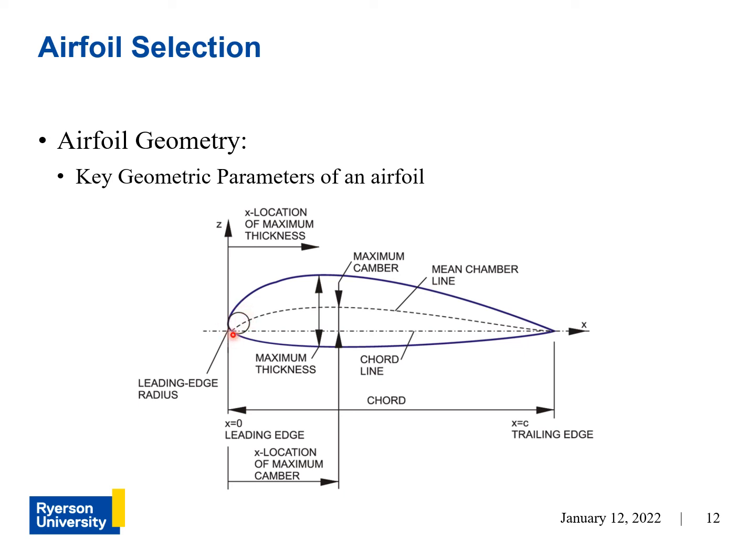Now, the front of the airfoil is defined by a leading edge radius, and you can see that here. This is the leading edge radius, and that's just defining the, I guess, the bluntness of your airfoil. So a large radius actually helps air stay attached at higher angles of attack, sort of the same as why you put a camber on your airfoil. It delays flow separation.